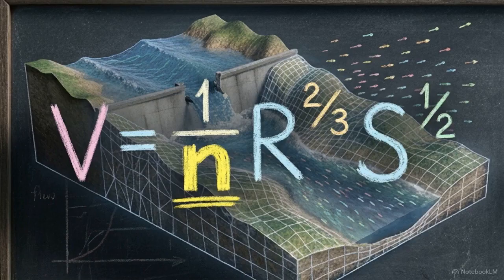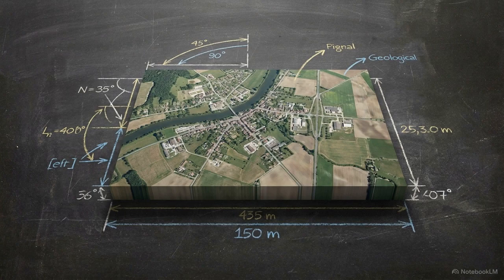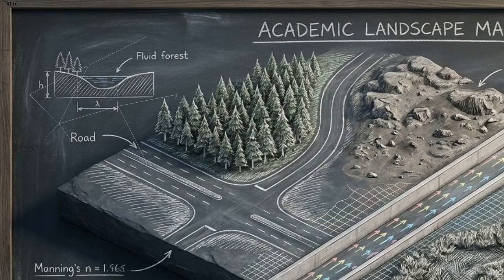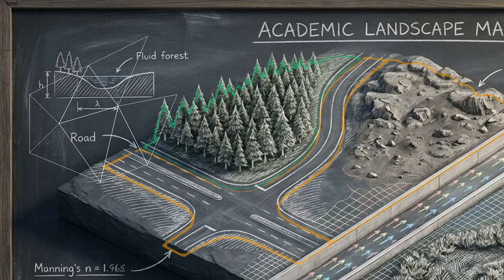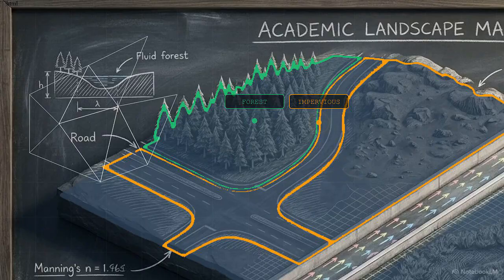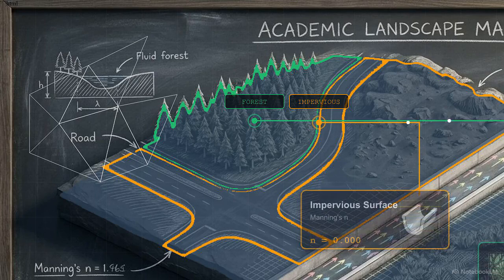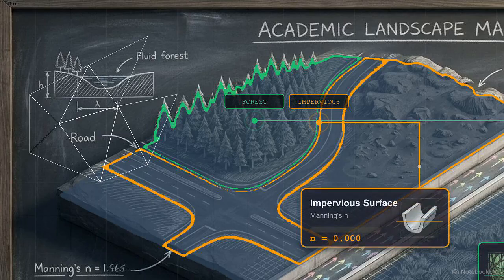To quantify surface friction, the software uses Manning's equation, relying specifically on the Manning's n roughness coefficient. Engineers generate a land-use land cover map by analyzing high-resolution ortho-imagery of the entire project area. The image undergoes vectorization, where distinct geometric polygons are drawn over forests, roads, and barren land, filling the map with distinct classification codes. Each polygon is assigned a specific Manning's n value. A dense brush floodplain receives a high friction value, like 0.15, while a smooth concrete channel gets a low value, like 0.015.